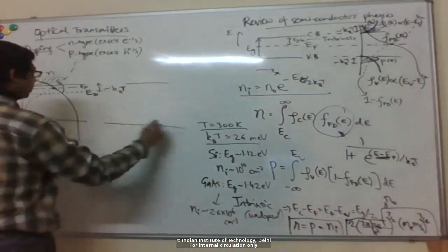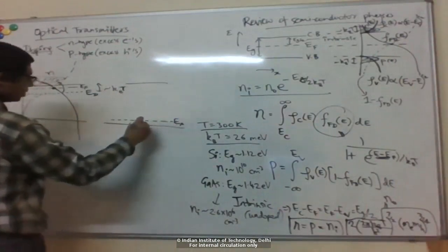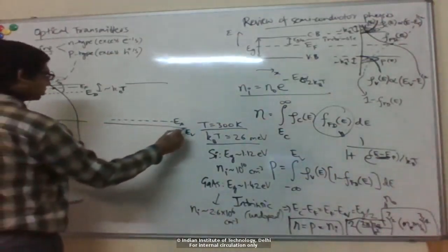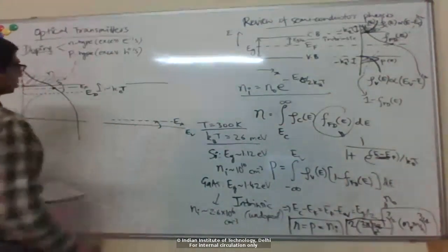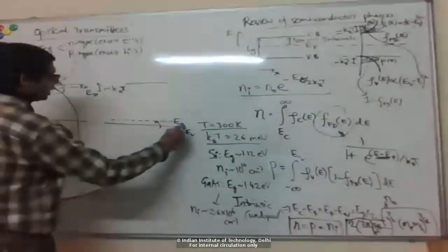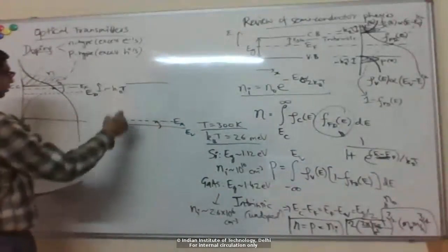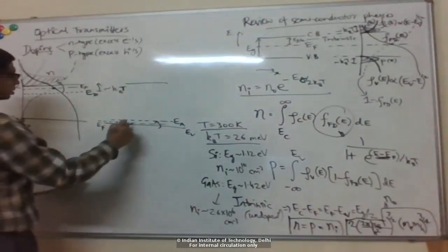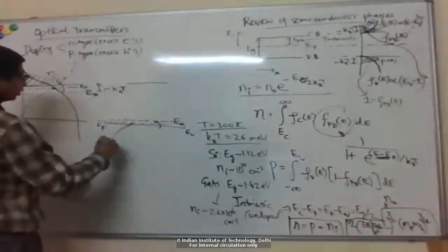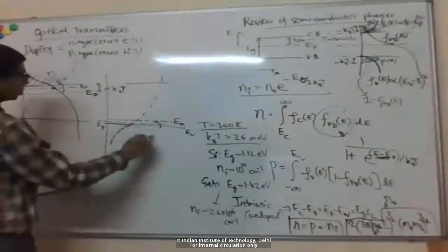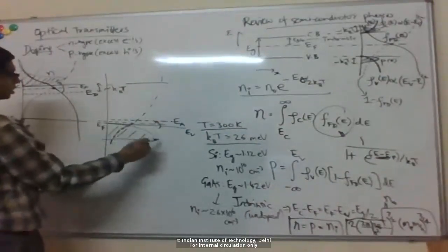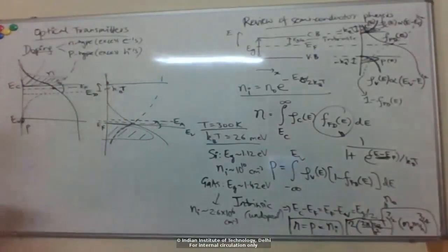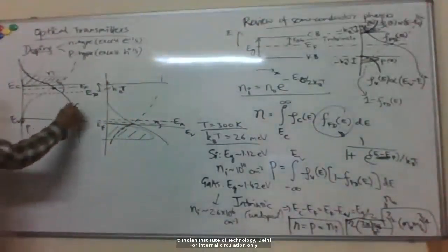And p-type is if you dope with an atom which has an energy level close to the valence band, and it's one lower in valency, so it can easily accept an electron from the valence band. So you can see now it easily creates more holes here. It's like shifting EF down towards the valence band. If you look at the holes, now there are more holes and hardly any electrons, because this distribution has decayed to 0 by then.